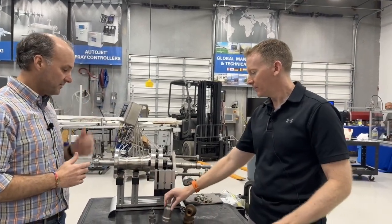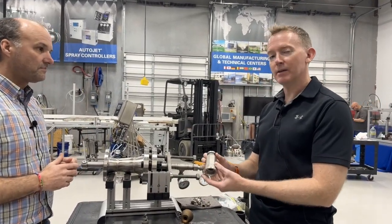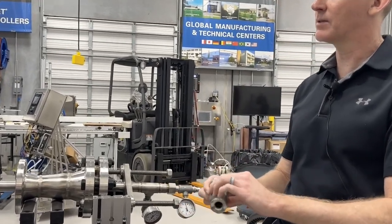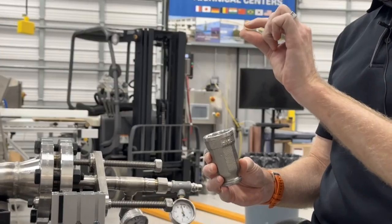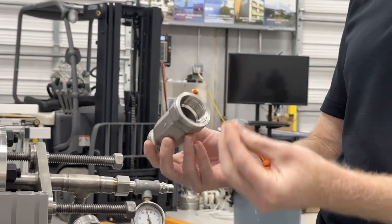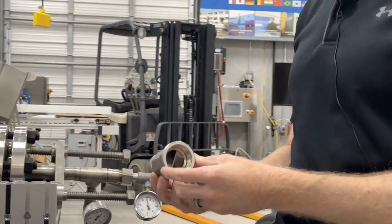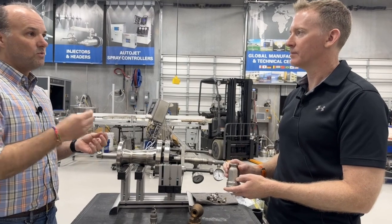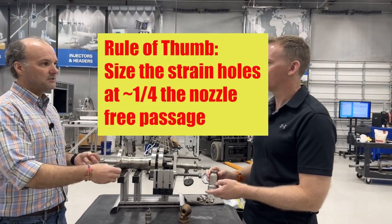That's absolutely right. And in our unit, in the delayed coker, we would normally specify a strainer upstream of this that has a hole size which is smaller than this free passage. So how do you select what the hole size should be? Well, from our perspective, as a general rule of thumb, we go 1/4 of the maximum free passage.